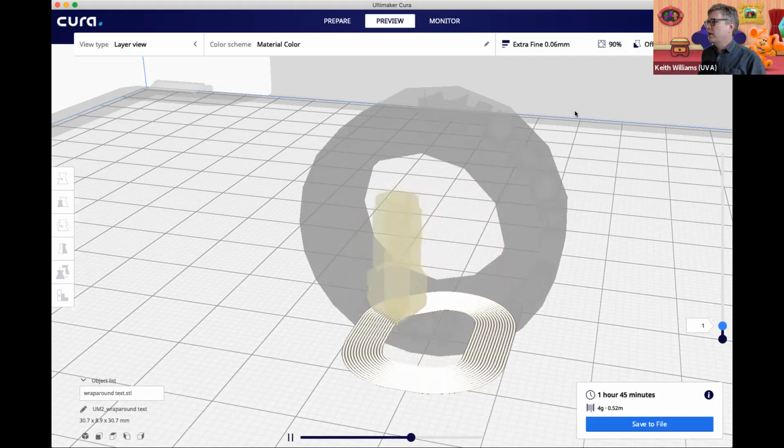So if you want to get the very best resolution, you have to actually have the nozzle very, very close to the plate. And if it's very close to the plate, then you can in fact get that kind of resolution. If you screw up, like if your print plate is a little bit at an angle or something like that, then the resolution gets screwed up and you don't get such a nice result.